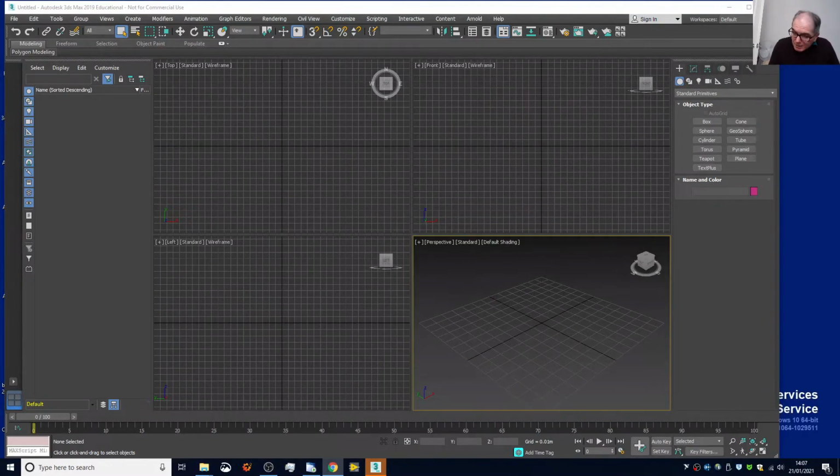And you can also use linking to get hierarchies, which allow children to inherit transform commands from their parents. So the transform that you do to the parents, especially when you do animation, for example, you move things around, is then inherited by the children. So if your door frame is a parent and the door is a child, you can move the child according to the parent, but you can also move the whole door frame, and the child, which is the door in this case, will move along with the door frame.